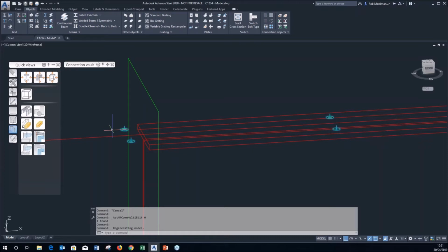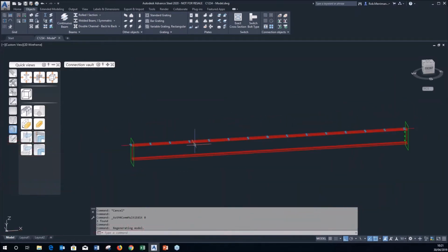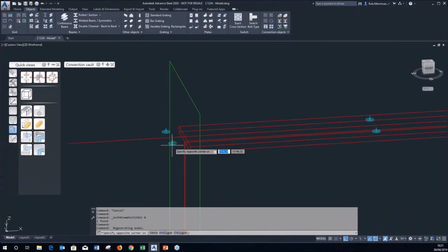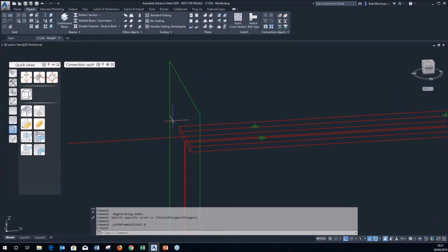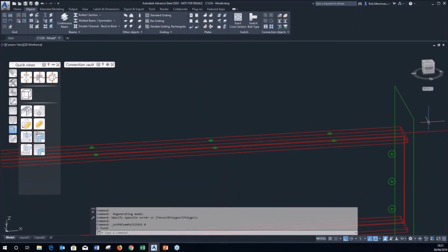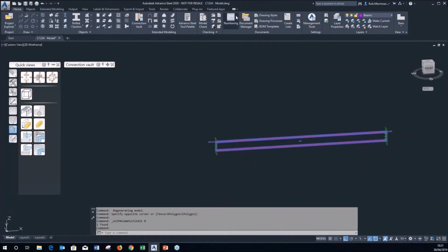But what we want to do is eliminate all of these errors so that I don't have errors in the NC files. And the problem is that these holes are just, the spacing's a little bit big on them. So if I change that to 375 maybe, that'll bring that in on each edge. And then if I run the steel construction technical check on that, just on that one element,